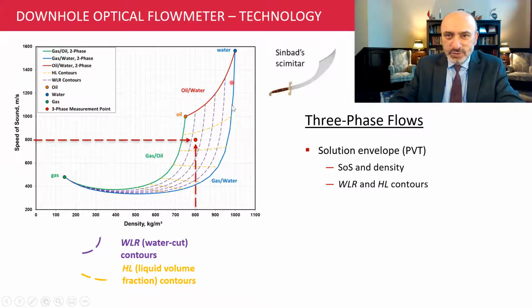We haven't talked about this, but this is essentially the same as the gas-oil one. It's a gas-liquid curve. So the only difference for these two-phase solutions is that instead of speed of sound versus density in the previous slides, we have plotted speed of sound versus water cut or liquid volume fraction. So essentially, they are the same.